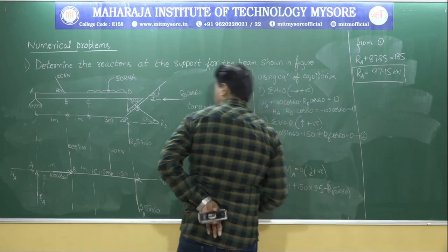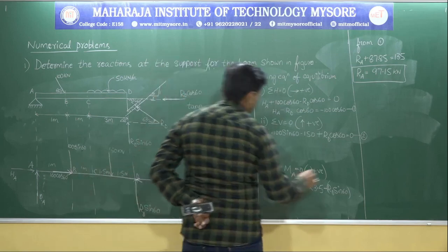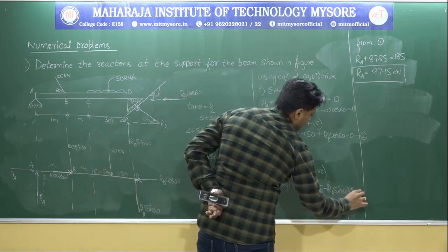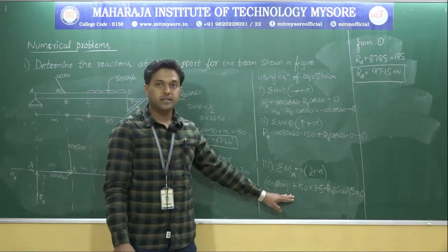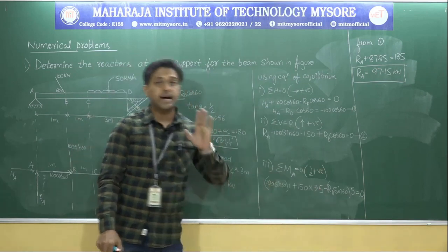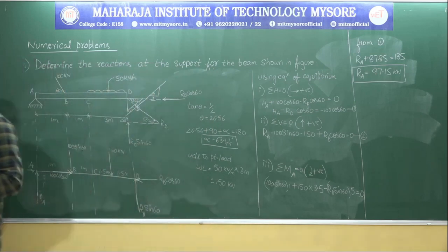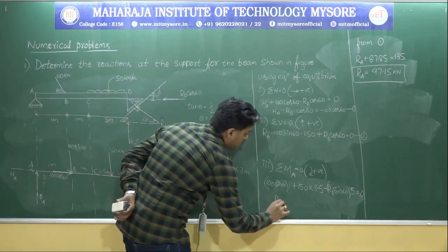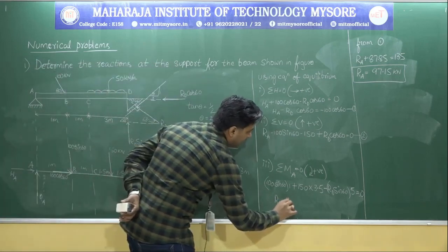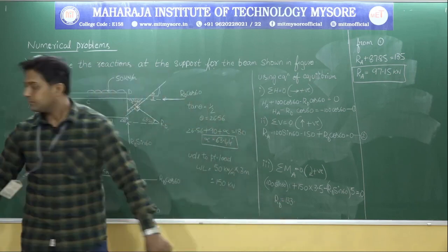Okay, into. So what is the total span? So it's 5 meter. So these are all the forces. Let me equate it to 0. Just by seeing this, you can say that there is only one unknown, that is RD. So using the calculator, what is the value of RD that we are getting? It's 133.19 kilonewton. So RD value is 133.19 kilonewton.